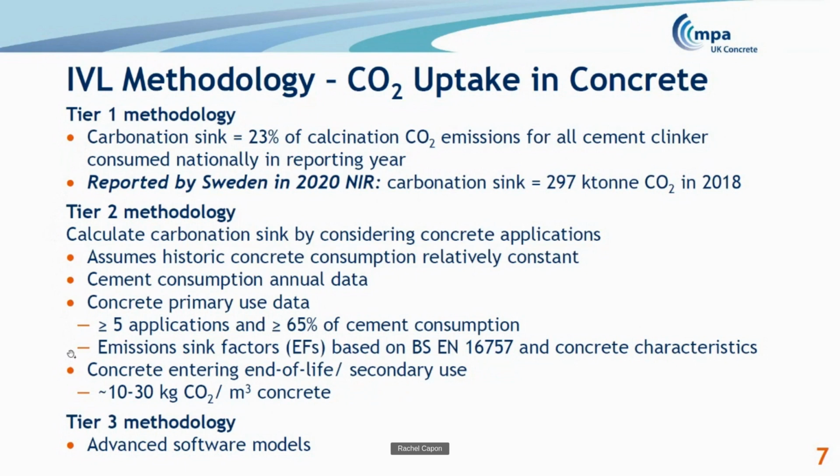For each of these applications, you would need emission sink factors, which are based on the EN 16757 methodology and the concrete characteristics. For concrete entering end of life or secondary use, the suggested CO2 uptake is between 10 and 30 kilograms of CO2 per cubic meter of concrete. The IVL methodology suggests that Tier 3 will be an advancement on this, but if we disaggregate the information further beyond Tier 2, then we're getting into the realm of advanced software models.